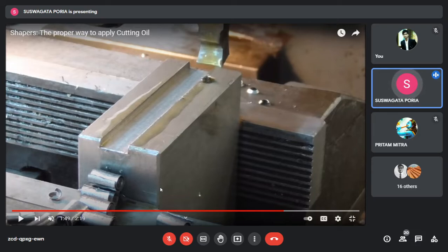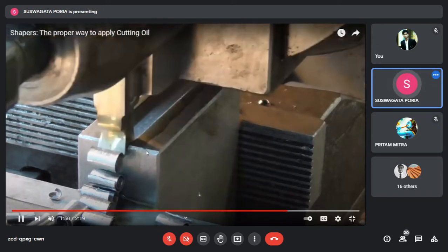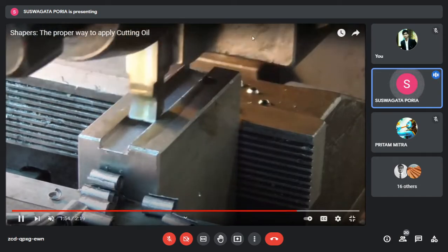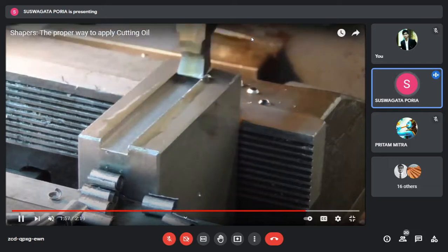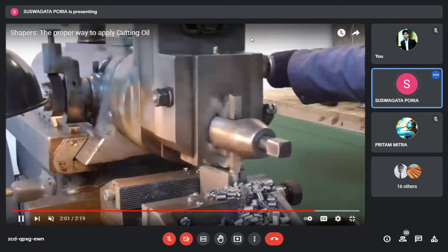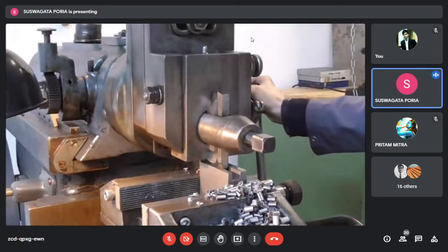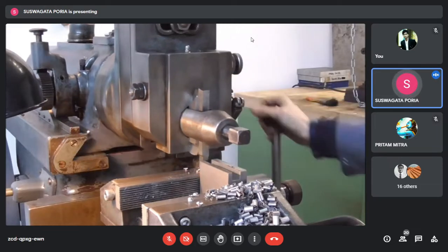If you practically see the cutting of the shaper, then all the time you will see this very minutely. This type of discussion would not be required then, because if I tell you, you can easily understand. As you have not seen it, that's why I have to explain it in detail. And you will always hear a sound, a tick-tick. It will lift up and get placed. So a sound of machining you will get because the tool is being lifted and then this plate is being placed in its original position. It is being lifted continuously, and this mechanism is performed by the clapper box. Okay.